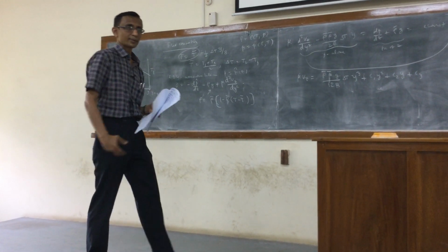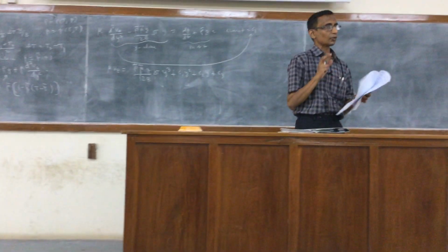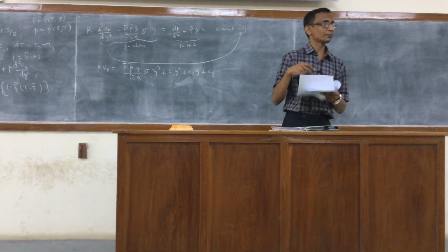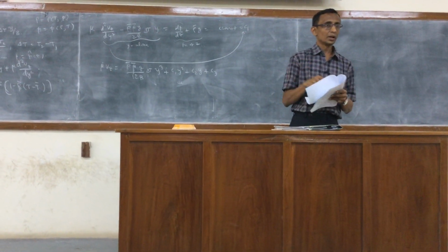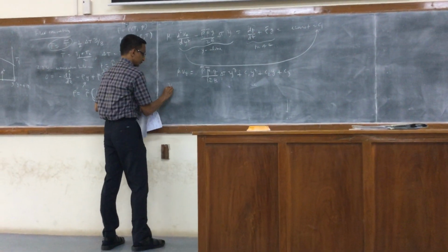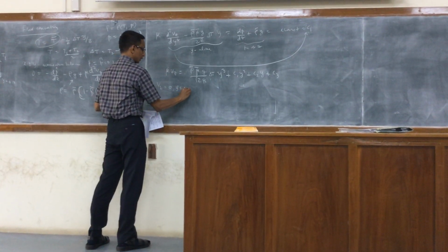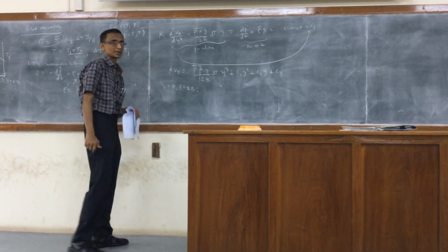Two of the constants, I said, can be determined by the no-slip boundary condition. Effectively, you can determine only one constant unambiguously, and we seem to get a relation between the other two constants. So if we set v_z equal to 0 at y equal to plus or minus b, those are the two conditions I get.